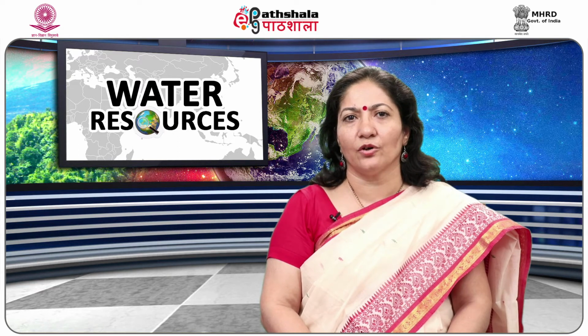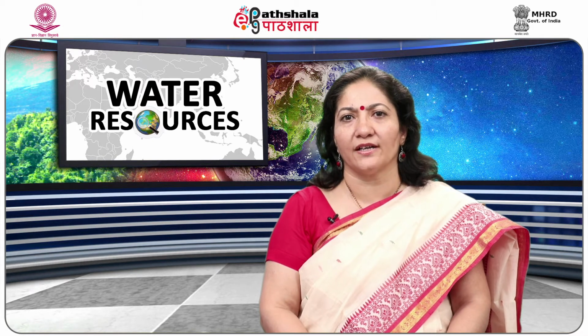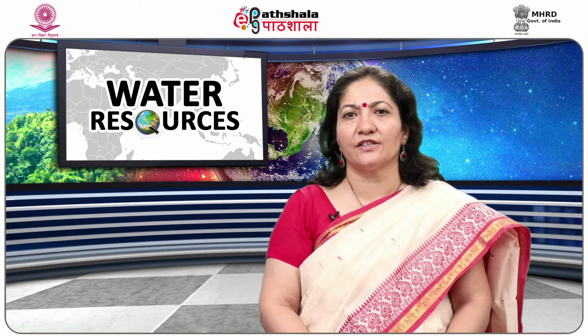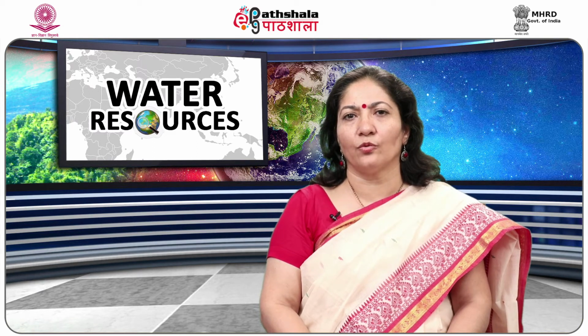The porosity of soil is the ratio of the volume of pore space in a unit of material to its total volume. The total amount of water that can be contained in the rock depends on the proportion of the gaps in a given volume of rock, and this is called the porosity of the rock. It is expressed as a decimal fraction or percentage. It is a measure of the amount of groundwater that is stored in the geological material.